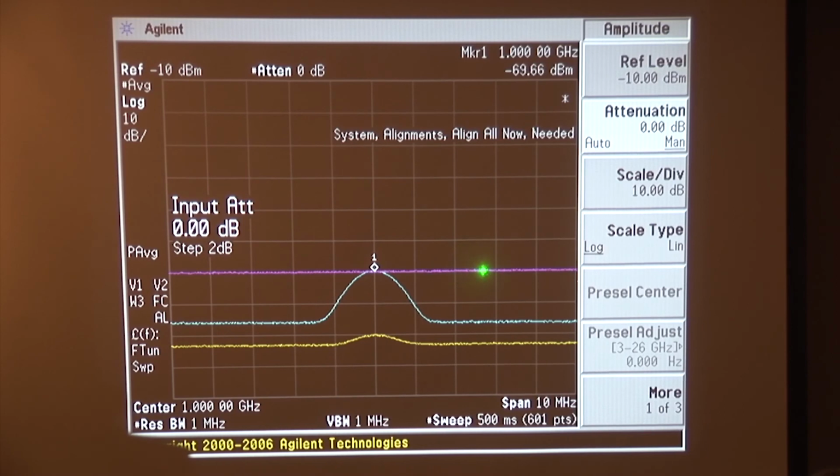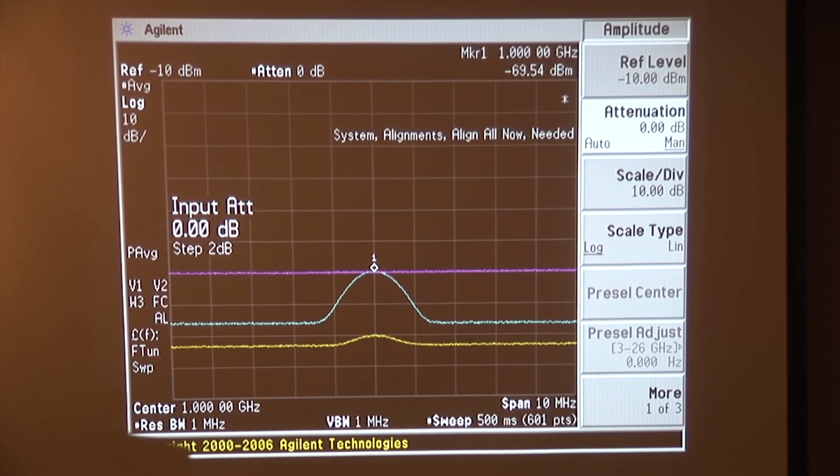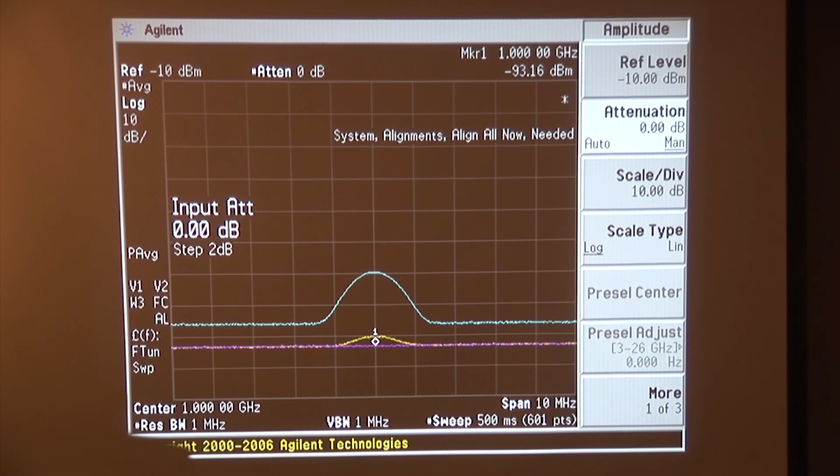Again, what I can do is just pad the output on this LNA with some attenuators. We would want about 23 dB of RF attenuation right here. So I screw together a pair of 10s, that's 20, and then I'll screw a 3 on, like so. And we've done this many times during field measurement scenarios. And then I'll turn off the power on the amplifier so I don't twiddle the power on these bare leads on the input and cause something bad to happen. Not that I haven't ever done that.